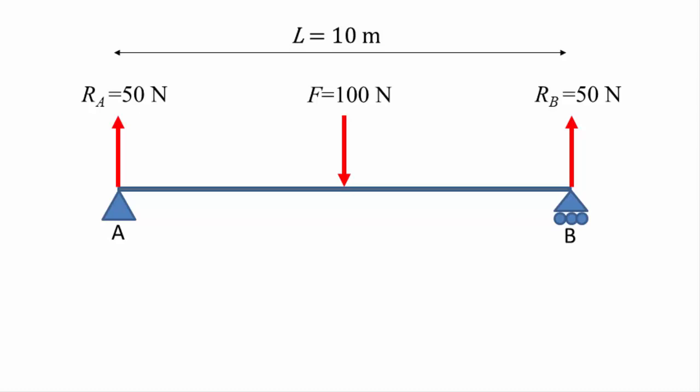Calculating bending moments is done in a similar way, where we cut the beam at the point of interest, look at all the forces before that point and how much bending moment each force creates about that point. The total bending moment at the point is the vector sum of all the bending moments from each force about that point. Let's start at the left end of the beam, which we take as the origin for our analysis.